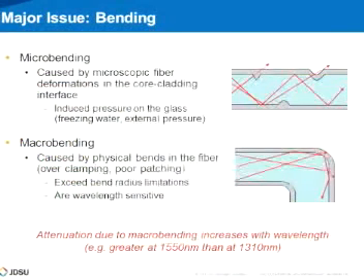So, just to repeat one more time, contamination and dirty connectors is the number one problem in fiber optic networks. And if you're installing the fiber, that will be the weakest point. The second one is microbends. Microbends are caused by external pressure, usually when water freezes and puts pressure on the fiber.